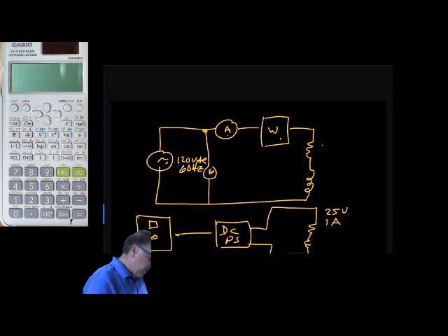And so from this we drew triangles. And on the wattmeter we were looking at 120 volts. We measured that. We had current, we had VA, volt amps, we had peak to peak, and we had frequency. So the reason why we had reactive power is because the power supply actually had an inductive component.